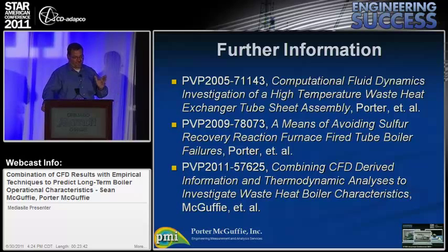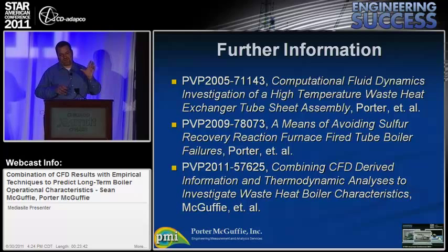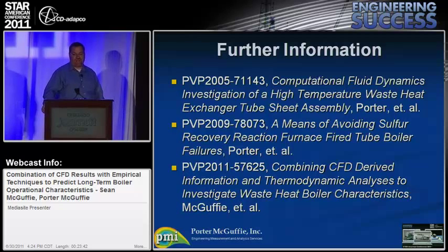We've done another project, and I haven't written a paper on it yet, where we did have to take a look at the mechanical interaction between the thermal reactor and the boiler, because obviously the thermal reactor is going to heat up quicker and introduce some bending stresses in. There we didn't include combustion because we knew the firing temperature, but we did have to model transiently the change in temperature of the gas flow through the thermal reactor and the radiation impingement on the inside of the refractory and how the metal temperature changed versus time.